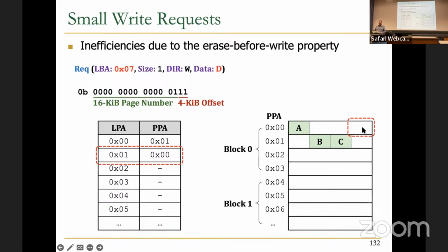But that would actually cause out of order programming. Because you program first physical page address 0, and then you program physical page address 1, and now you want to get back to physical page address 0 for this program. So that can cause issues.